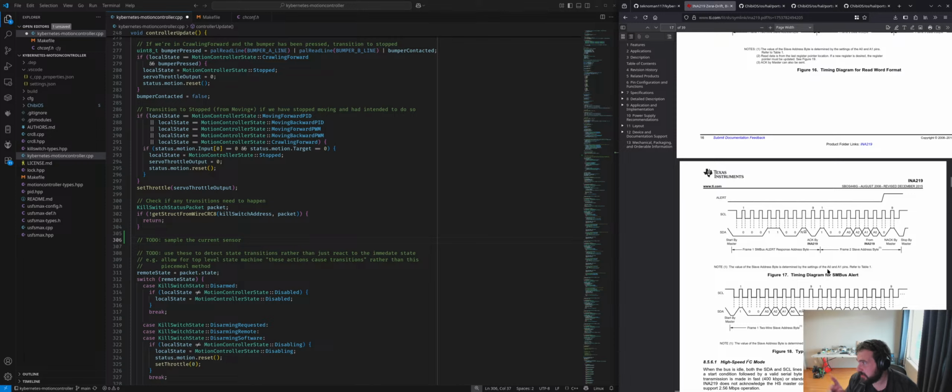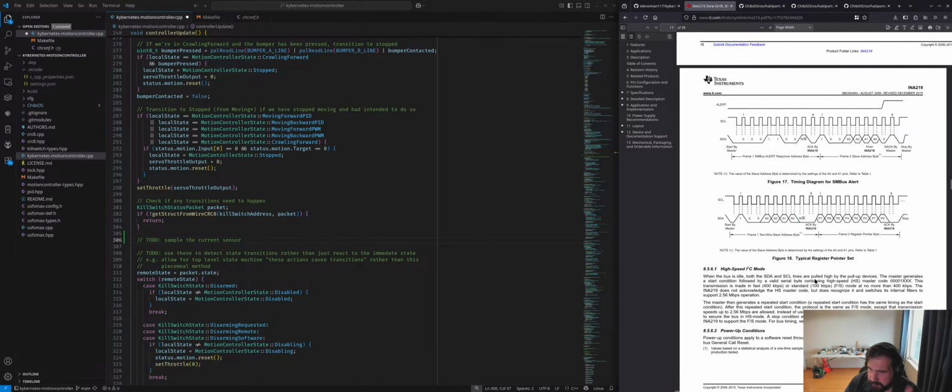That's one thing that SMBus has that I2C doesn't. It's not particularly well defined how I2C devices generate interrupts. Theoretically, you can do something based on pulling the line low to send events, but I believe SMBus actually has a mechanism for sending interrupts over the I2C lines, but we won't be touching that.